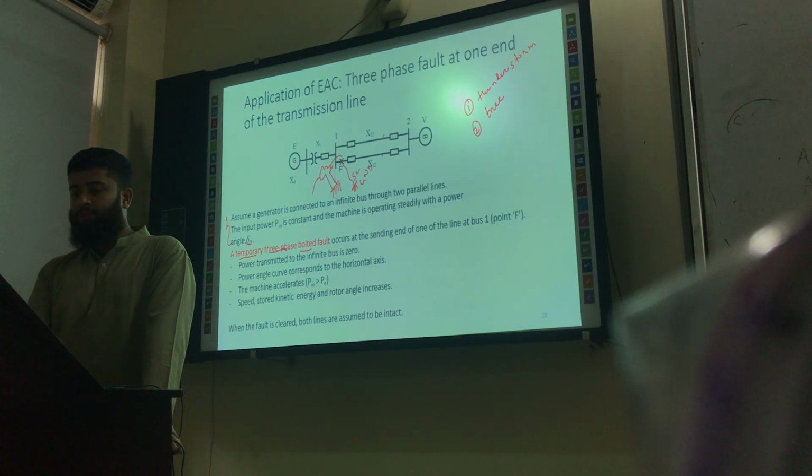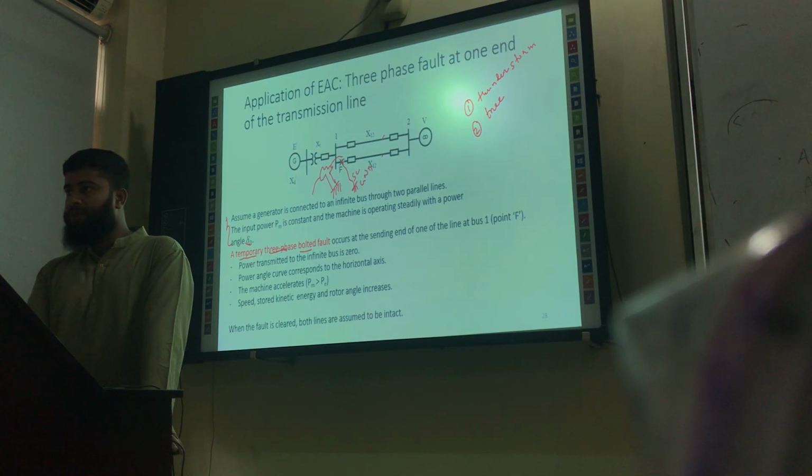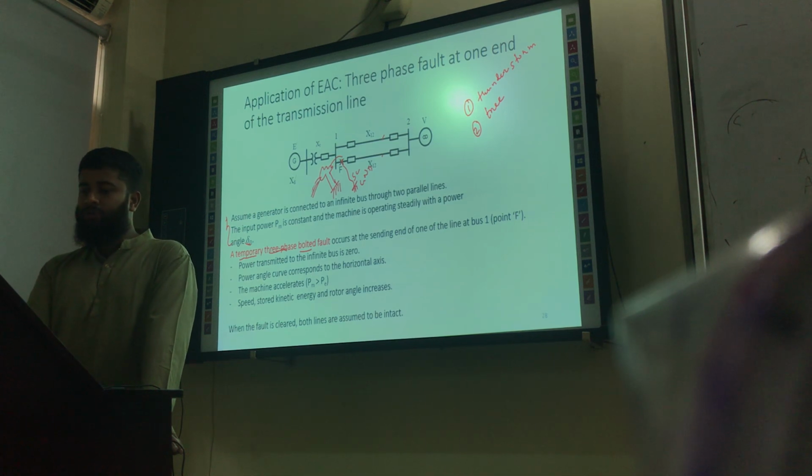Whenever it swings to the right, it touches this point. This tree is connected to the ground with its root, right? So whenever it touches this point, there will be a short circuit path to the ground.